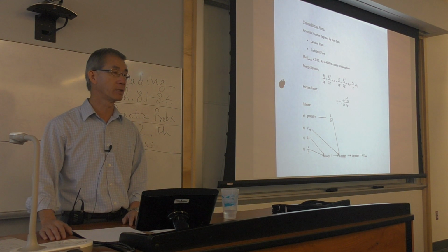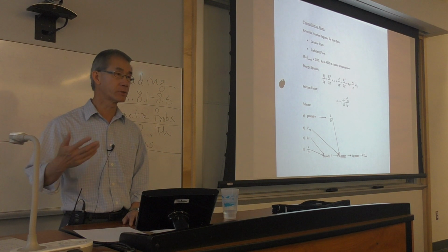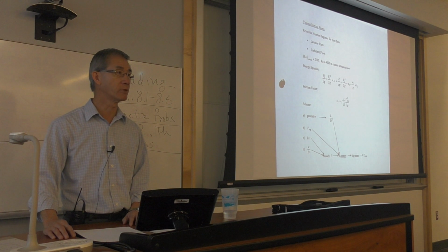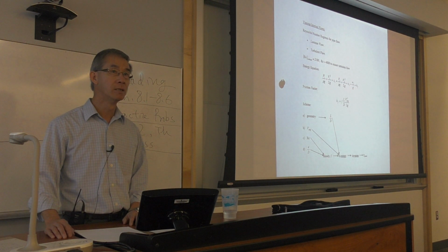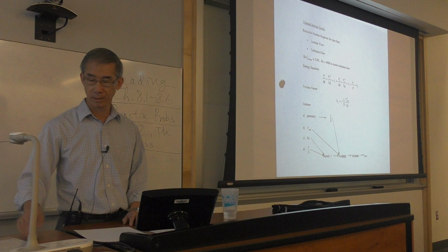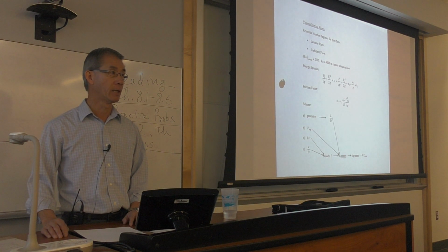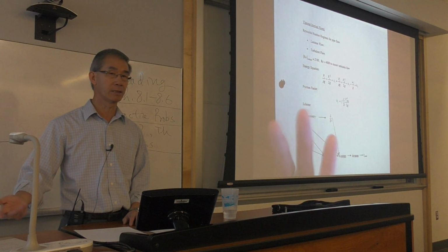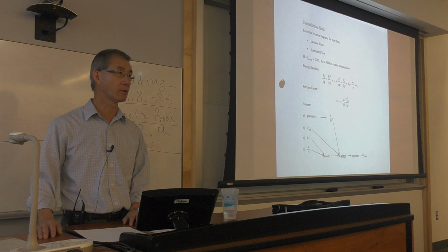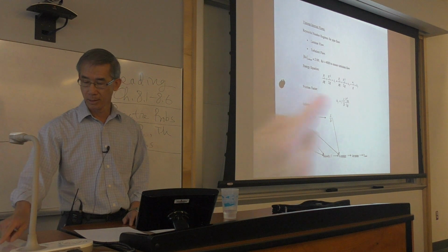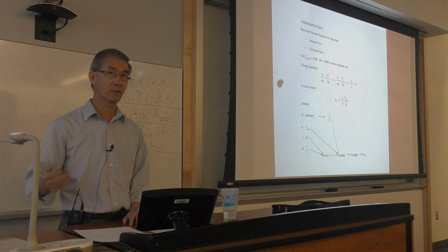It's a very specialized form of the energy equation that's only used in pipe flow, but very practical, because it relates my frictional losses, in terms of an increase in internal energy or an increase in entropy, that's the h_f, and whatever device or machinery that transfers work in or out of my control volume, a pump versus a turbine, and that's this term. Are you comfortable with that?